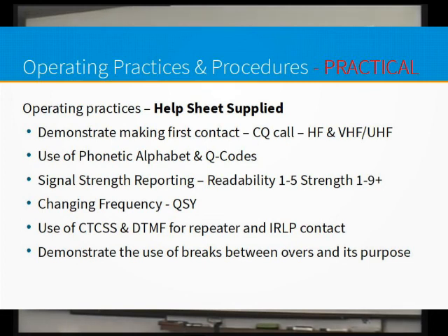Sorry, is that to stop a rogue transmitter from just holding the repeater for a period of time? Yeah, that's right. We had one a couple of weeks ago, didn't we? Somebody had their... Yeah, a day and a half. Day and a half, was it? Oh, yeah. Jeez. Obviously it didn't have a timeout. No, there's usually what they call a watchdog timer on it, which is what you're talking about. So it resets after a certain period of time. I'm guessing if for some reason someone's mic has gone open circuit, it's just going to keep the transmitter on. Like in this case, somebody had their transmitter jammed on.